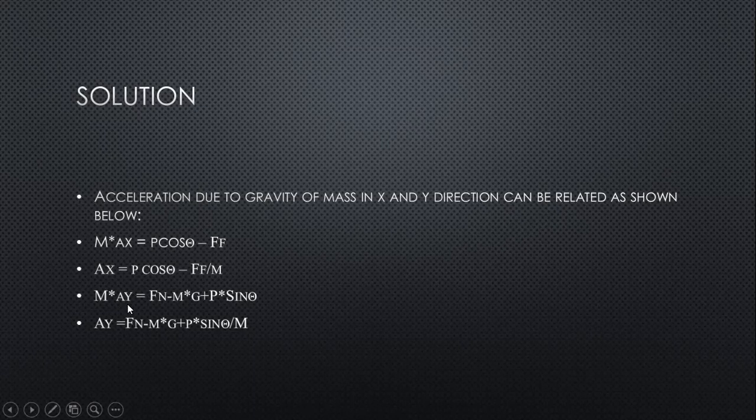Similarly, m ay, where ay is the acceleration in the y direction, is equal to Fn minus mg plus P sin theta. So ay is equal to Fn minus mg plus P sin theta, divided by m. So ax and ay are the accelerations with respect to the x and y directions.